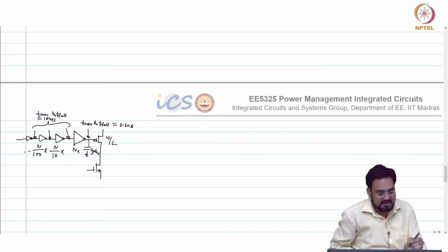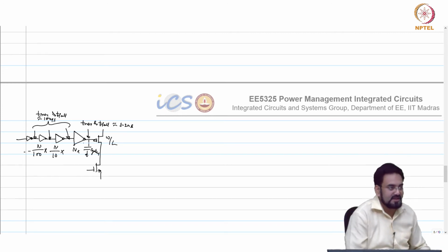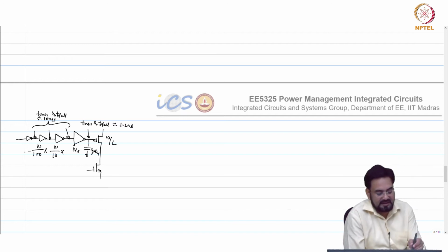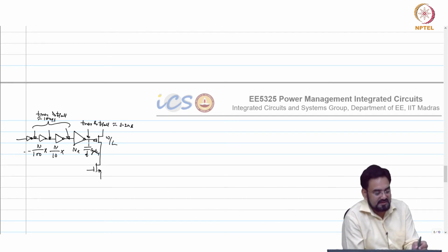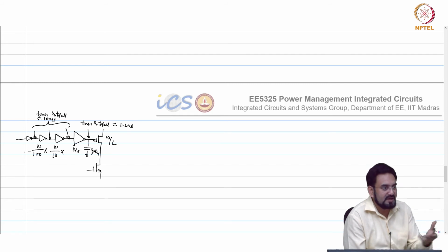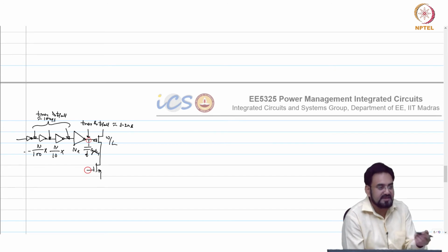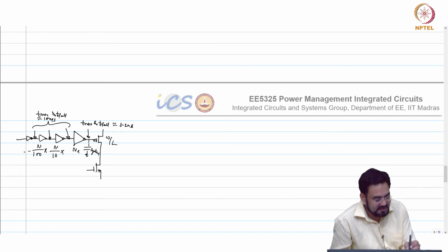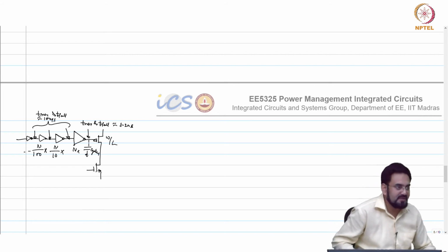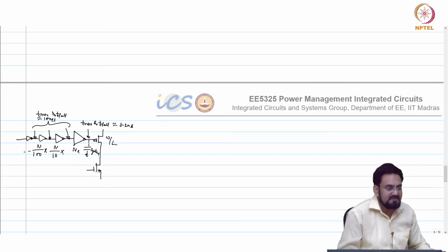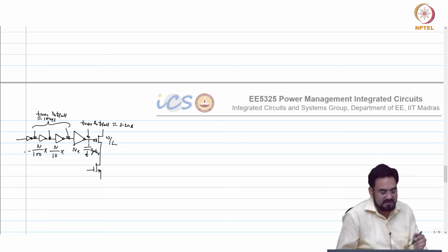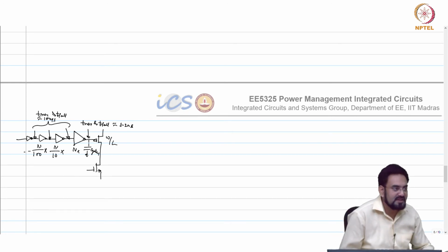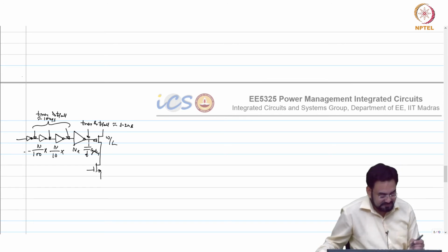So you cannot say that whatever the size of this, you can simply scale down. You look at the cap here, but after that all the devices are the same, complementary NMOS and PMOS with the gates shorted. Here the gates are not shorted, so the same formula cannot be applied. That does not mean you can just divide by 10. It may be even larger, maybe 50 times or so. Whatever the size of this, divide by 50, something like that, W by L.